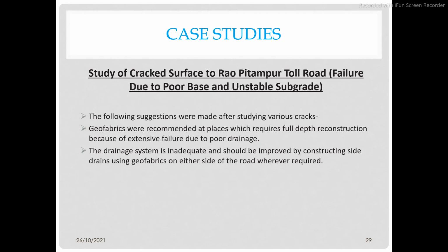So these are the suggestions made after seeing the various cracks. Geofabrics were recommended at places which require full depth reconstruction because of extensive failure due to poor drainage. The second suggestion is that the drainage system is inadequate and should be improved by constructing side drains using geofabrics on either side of the road wherever required.